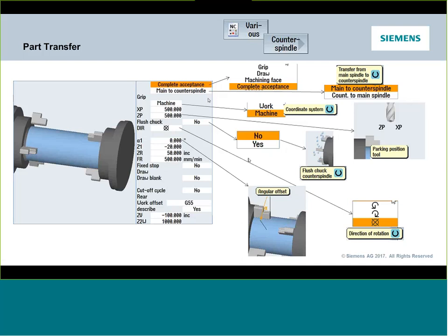Now, you may not know if both spindles are at 0, if those jaws could collide, so that's usually the first thing you got to figure out. But once you know, you can put some offset to them. So potentially you could have the two jaws nest within each other during the transfer process, and that's perfectly fine and actually very typical. That's what this offset comes in for.